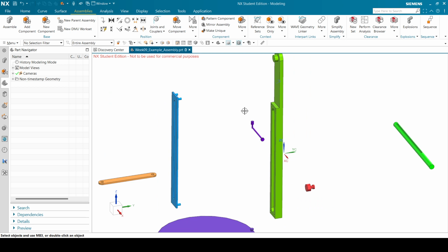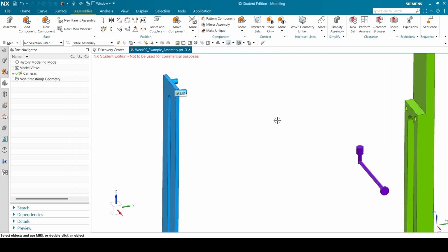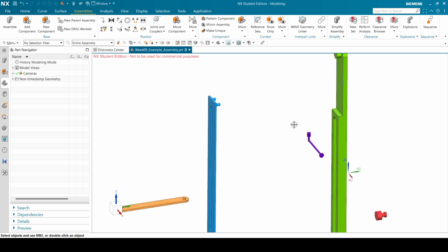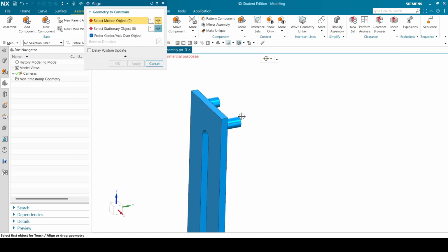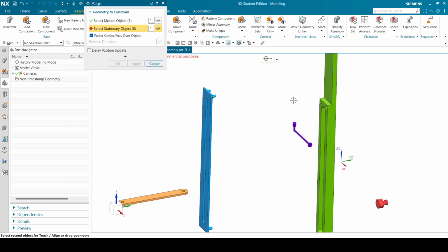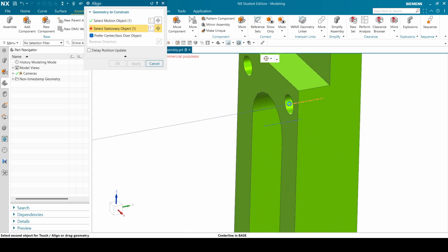that's what will happen when you do it on a physical part. So I could also align these sides with these sides, but that's not very practical. You have to try to constrain it the way that it would be constrained physically, because then usually things go better, so it breaks less easily. Okay, so I'm going to say align, and then we're going to align the central axis of this to this axis.